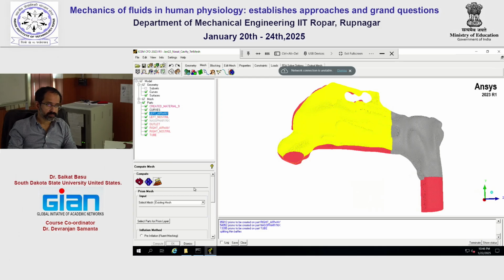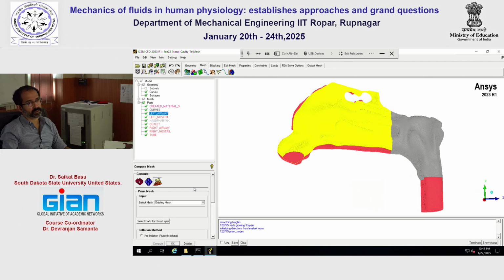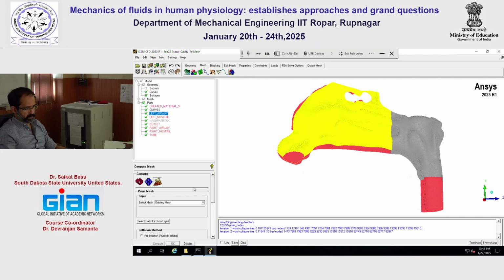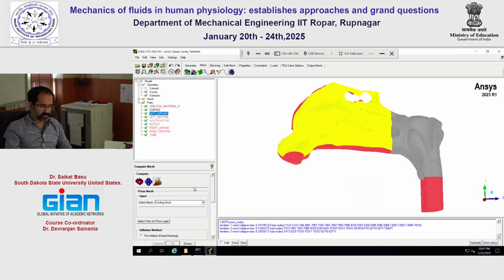Like for example, in this we have a shot. I have seen one where they exclude the internal volume of the shot and only mesh the ICM, but here we are not doing it that way. What tool do they use for the meshing? Is it a 3D mesh or a 2D mesh? 3D mesh. The prism mesh typically takes longer because now the mesh is getting more refined in certain regions.